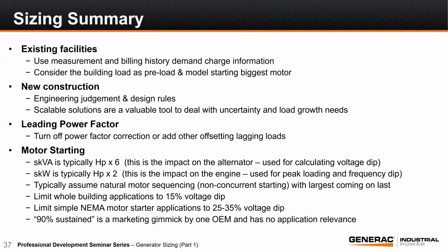Thank you. There was a question. You mentioned generator paralleling and planning for future growth. What considerations do you need to take into account if you're paralleling generators as far as sizing? If you know that you're going to be expanding, there's a couple of different things when you're doing a parallel system that come into play, such as, are you looking for redundancy? Once you expand, are you keeping in mind how much real estate you have when you're looking into the future, to make sure that you're sizing based on the space that you have, basically.